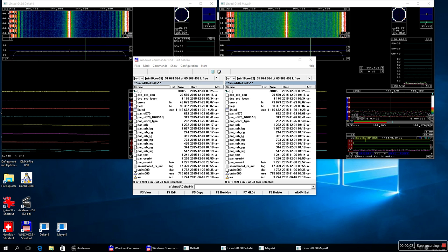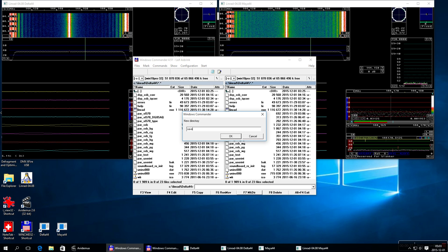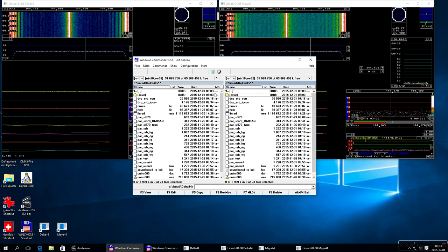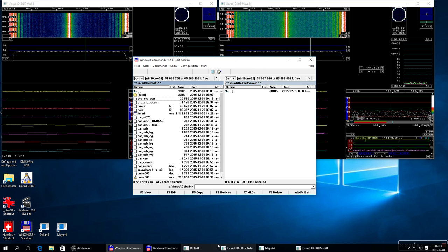The next step of the calibration procedure, removal of the center discontinuity, is going to change the calibration function. So I save the functions I have now produced, make directory save, and copy the frequency response calibration here.